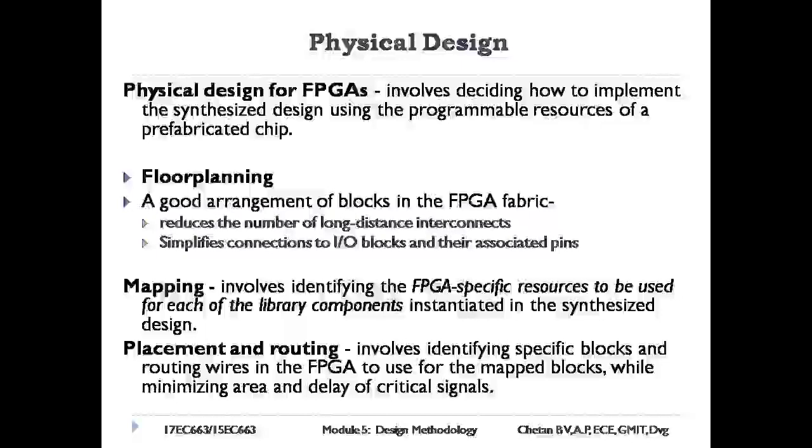In the EDA tools, constraints on placement and timing can be specified to improve placement or routing. The final result is a bit file specifying how the FPGA is to be configured. Detailed timing information for the design can be generated based on the internal parameters of the logic blocks and interconnect in the FPGA. Final timing simulations are performed to verify that the implemented design meets the timing constraints.